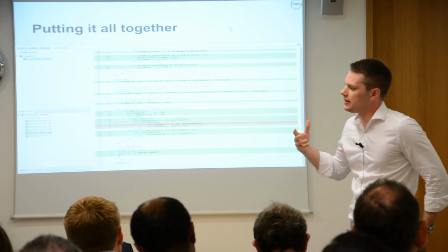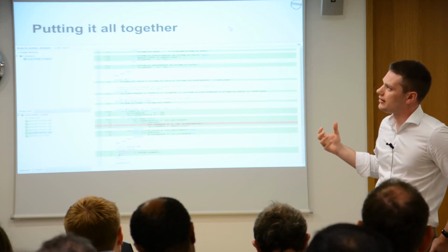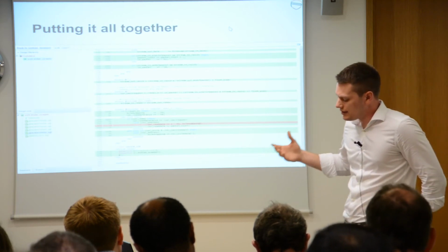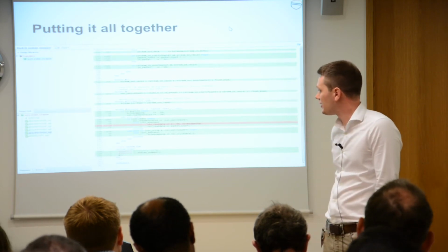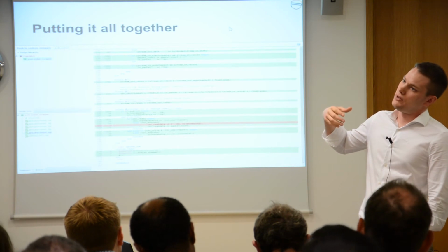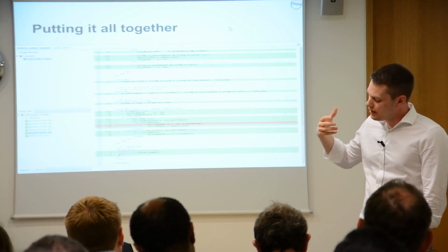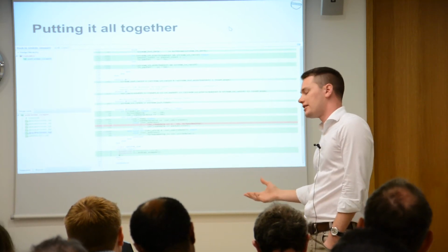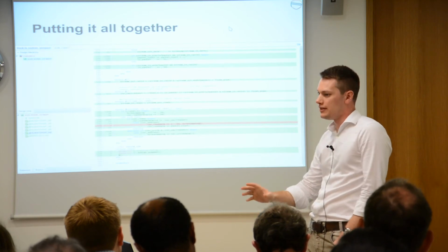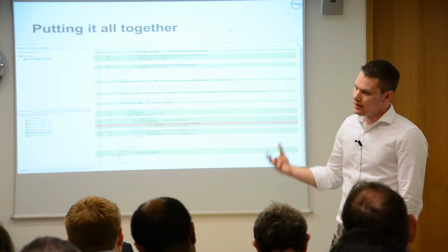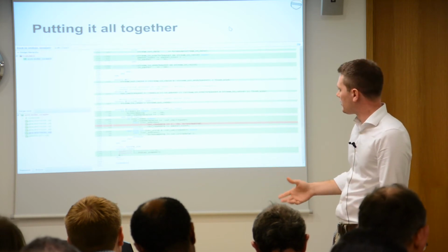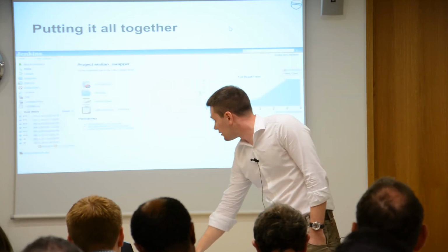It's a philosophical thing as well. With Cocotb, we've gone for making it easy to write tests, so you can create a test bench for even the smallest piece of code. The overhead of creating a test bench is very low. We output test results in JUnit format, so it ties into Jenkins.